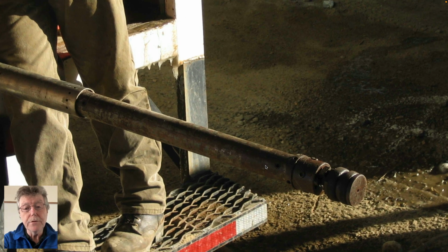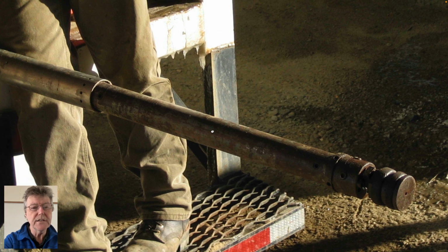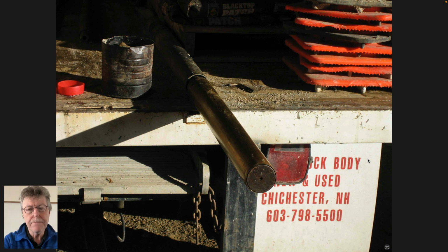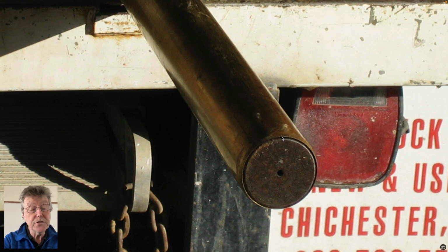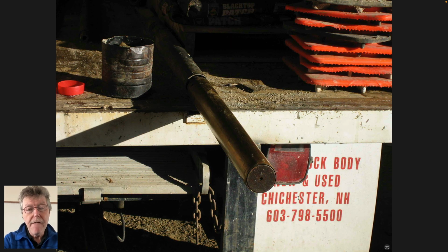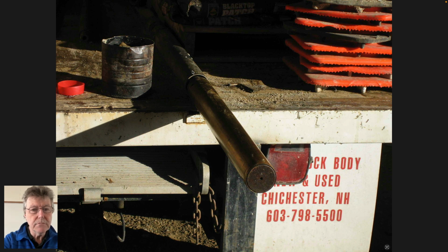All right. So we talked about thin wall samplers. So this is exactly that. This is a piston sampler. This is a piston that's on a length that is now retracted into this housing. The idea is that onto this coupling here, you'd slide a very thin-walled sampler, which is this. You perhaps can't see it really well, but this is a piece of brass tube. It's probably a tenth of an inch thick. This is that piston that you just saw advanced to the end. This is at the bottom end of this tube. This coupling here is actually up here.